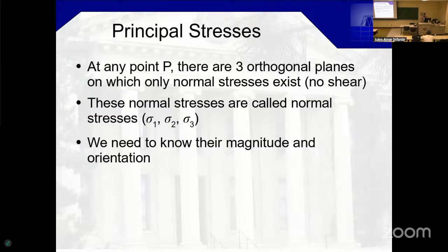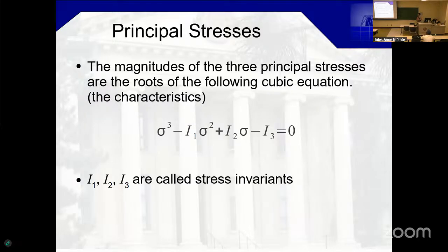you can express your operations at the end of all that with, so if sigma here represents the terms of your eigenvectors, in the case of a state of stress, you will always find that the three roots of this polynomial will give you your three principal stresses. So if you solve for this cubic polynomial, you will always be able to find sigma 1, sigma 2, and sigma 3 by solving this equation.